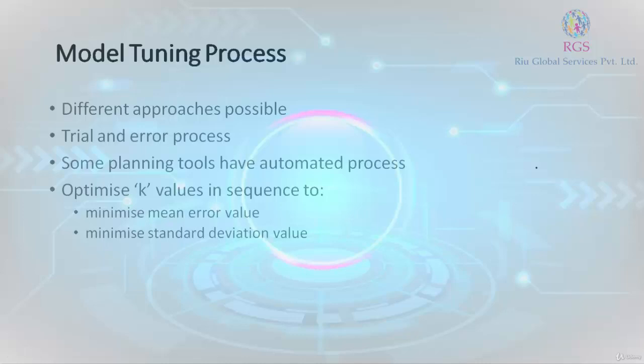Okay. So once you collect the data, after that you may need to filter out important information only, right? For example, if you're doing the drive and there is a road which is blocked, on this you got too many signal sample values which are not required, so you can filter them, saying I will consider the signal only after 5 meters, or usually 10 meters is the filtering distance which we consider. 10 meters, 5 meters.